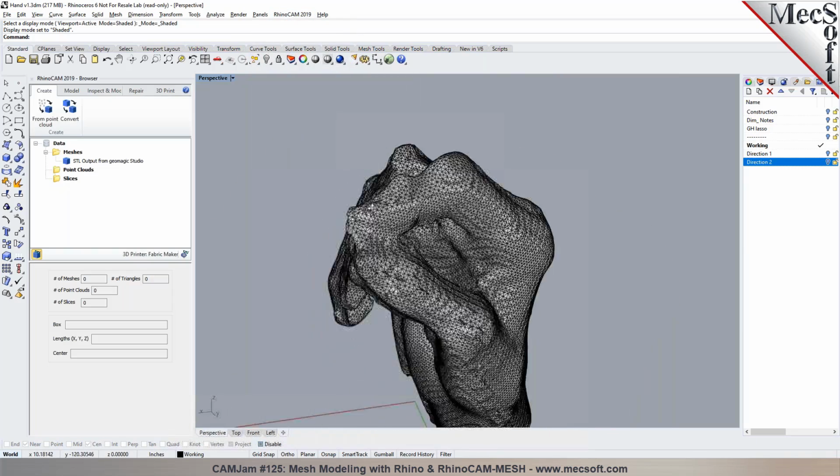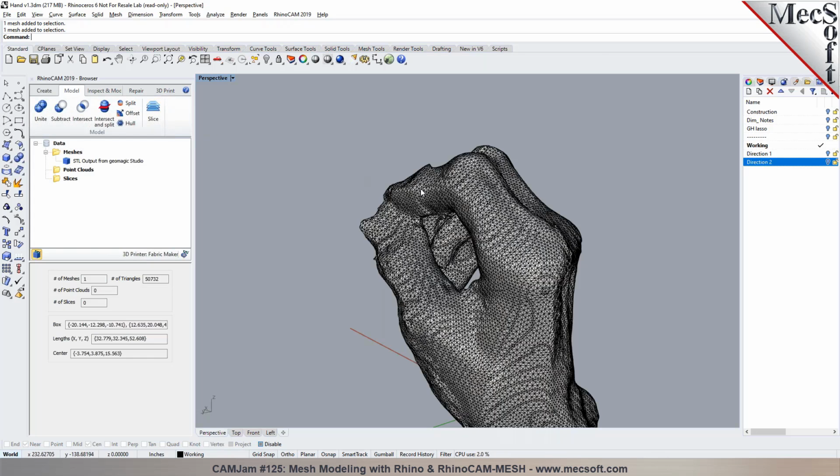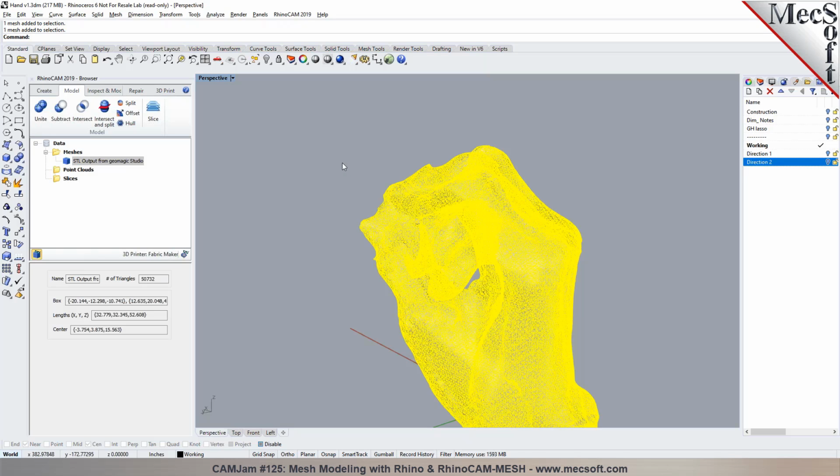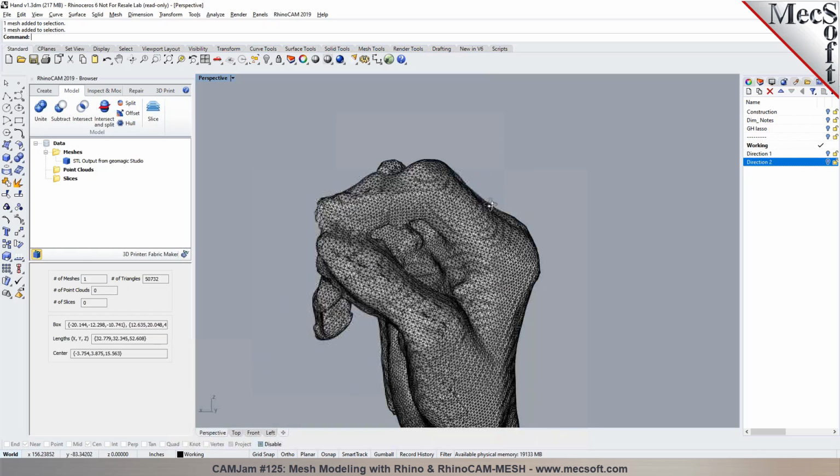Okay, so we wanted to offset this mesh. So you want to have like a thickness to it, right? Like a wall thickness? Well, that's a good question. If you offset it, it turns it into a solid. Well, we offset only closed meshes, not open meshes. But if you want to do offsetting of open mesh, Rhino has some offsetting tools for that. So typically, the whole point of offset is to create like a wall thickness or a shell. You can do it so when you 3D print, you're not basically filling the inside volume completely. Yeah, right. Okay, all right. So the offset's not used to make the thing bigger. It's just used to, like you said, shell it.